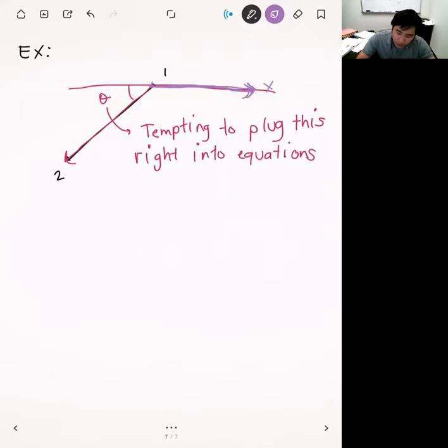And then the angle that you should plug in is actually going to be what it takes to rotate from the positive x-axis over to where your vector is right now, okay? And so in order to get to this orientation, we have to rotate all of this amount, okay? And so the true angle, the one that we actually plug into our element stiffness matrix, is we rotate 180 degrees, okay?